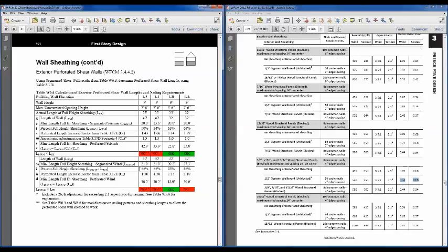We've got a whole lot more wind and seismic load on this structure, and you can see that those required wall lengths have just increased pretty dramatically from those tabulated values above. But there's a way, because we're still at pretty much 6 inches on center spacing for all those walls.